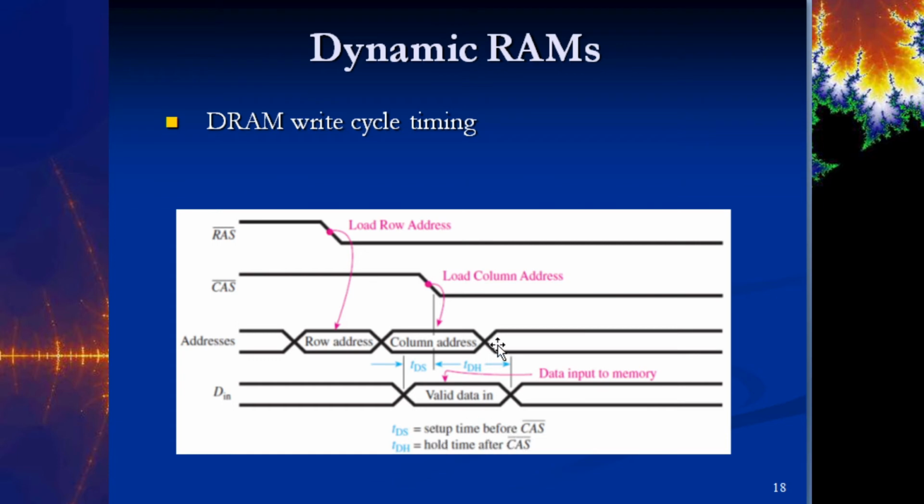Okay, now the hold time just depends on the family, what that is. We saw in some cases it could be 0 seconds. So it just depends. You have to look and see what this is. But anyway, it will accept this data in as long as it was stable for this setup time, and then it holds stable in this hold time after we have had our row address and our column address strobes.